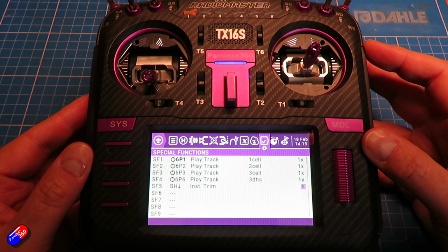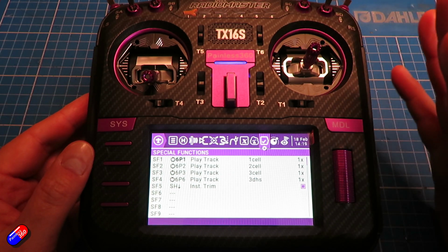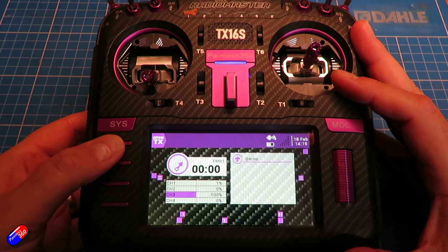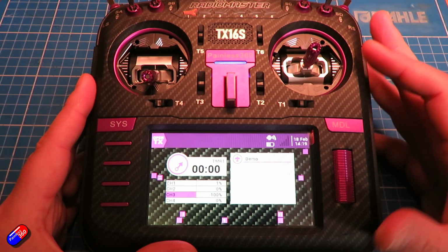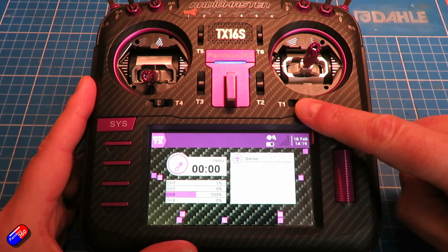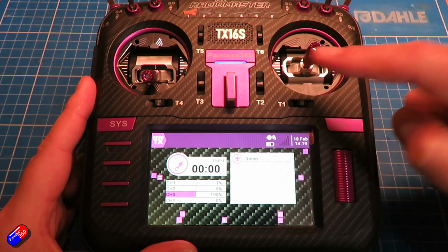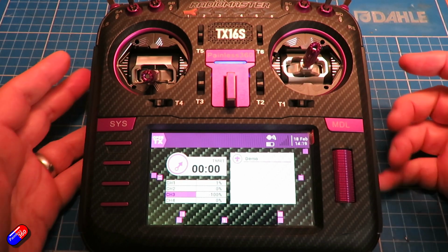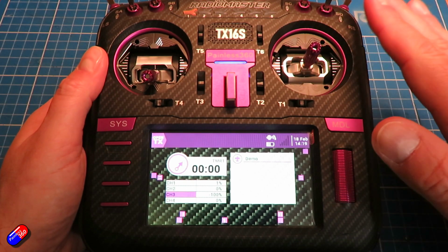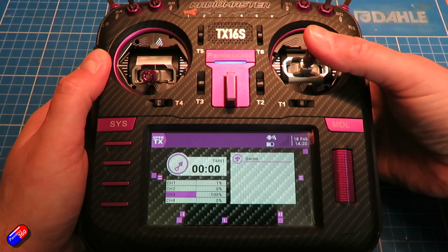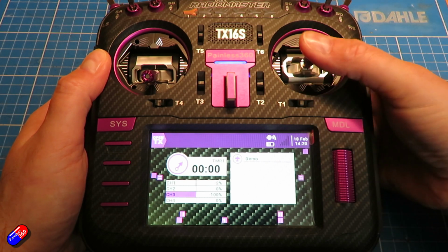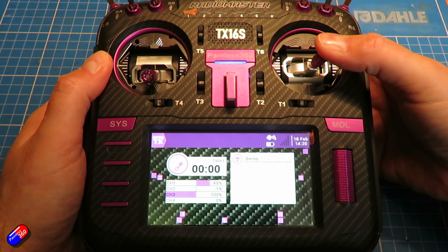However, that's not what I want to talk about today. This is for a Patreon of mine called Ulf, and he's talking about cross trim. Now, the reason that cross trim is an interesting thing is because normally the way it works is the trim for the aileron is this trim here. The trim for the elevator is this trim here. Now, that's fine, but the way it works is as you're flying, maybe, for example, the model is always tilting to the left-hand side, so you need a bit of right trim. You'd put in a couple of clicks of trim down here. But to do that, you'd have to take your finger off the stick.